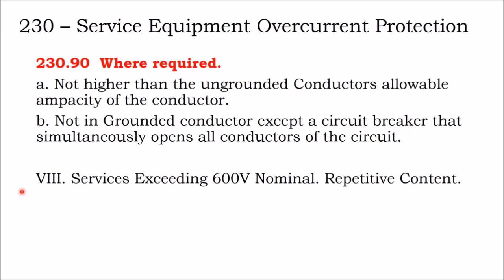That's okay, that's allowable, but if that's the case, you need that breaker to simultaneously open all the conductors, not just the neutral wire, but also the positive and negative as well.